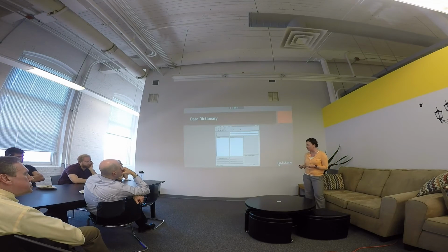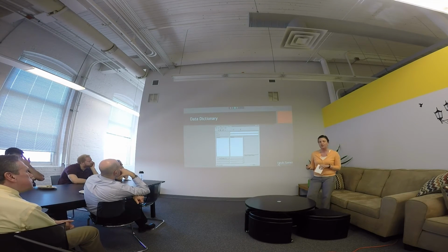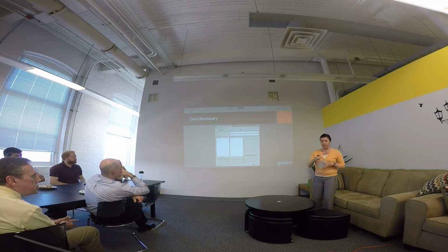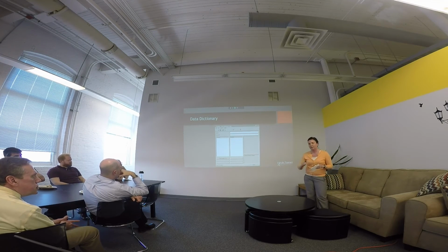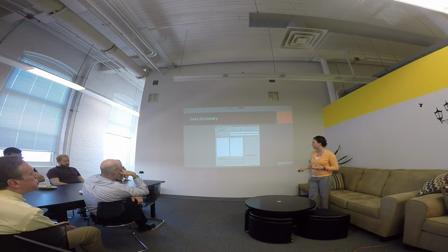Basically, it's a database that works with GIS, and it works based on existing features and attributes. So if you already have your system in GIS, you can bring that to the GPS, basically update attributes, update locations if they need to be updated, and then it goes all the way. It's a database, so it's really powerful. Sometimes it can be overkill for a small project, but it's great for asset management. And I'll show you some examples.